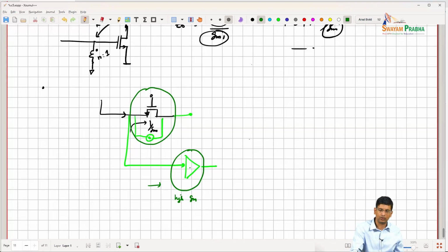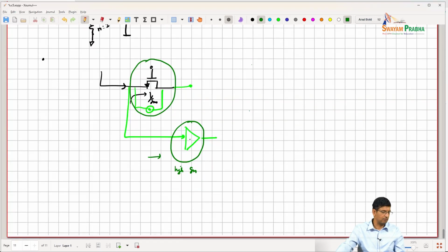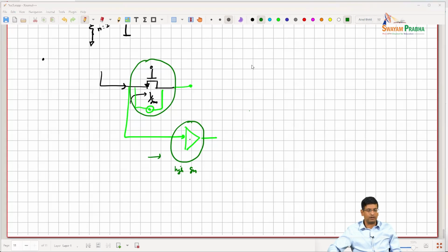But the cost usually is power consumption, right? So what we see now is that at millimeter wave, such topology is also appearing where we have noise cancelling using this type of transformer feedback approaches as well to get wide bandwidth and low noise figure at the same time. So from a system perspective, we've seen numbers like 2 to 5 dB when we build LNAs at these frequencies.